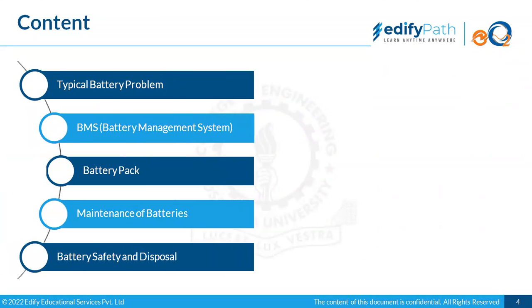In addition to what we have discussed, the data sheets were to give you an idea about the selection of cells when you are going to assemble a battery, and what parameters you should know about the cell. We already discussed that we are limited by the smallest unit in our battery, the cells.